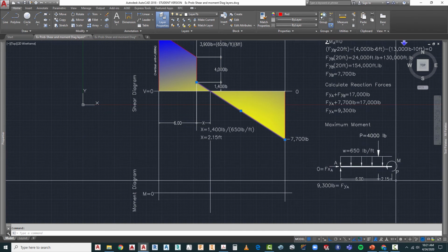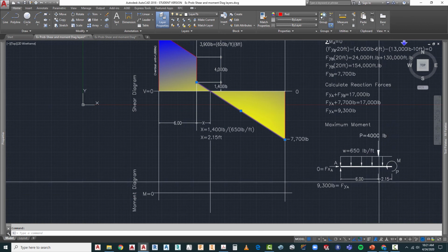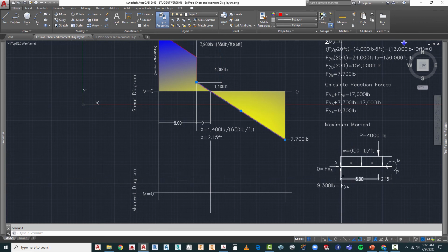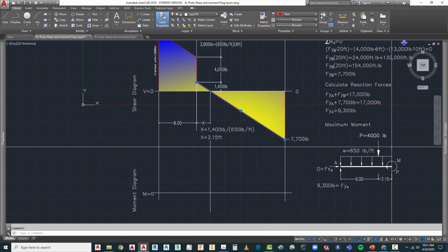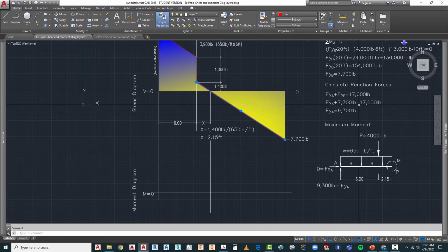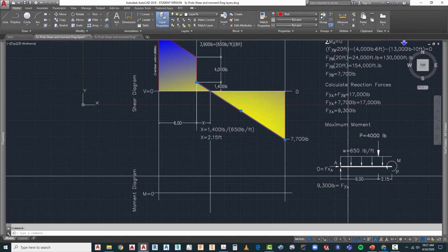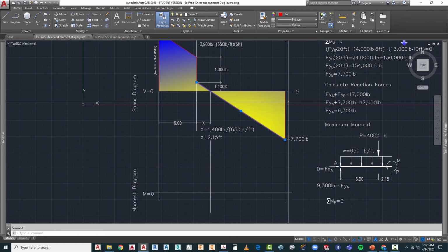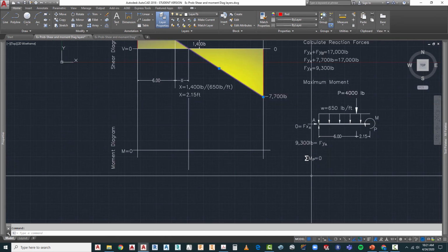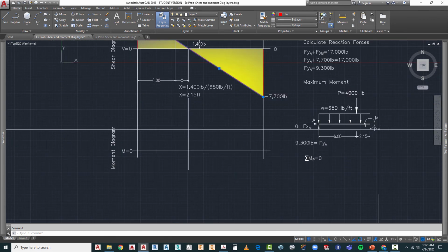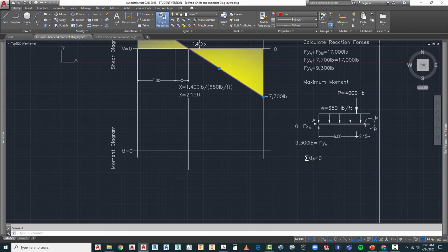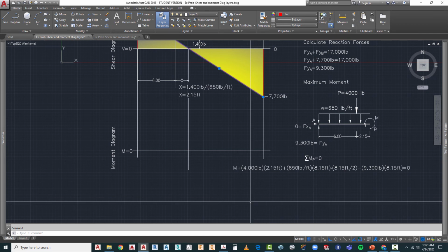So what we need to do is we have established where that concentrated load is going to be, and we have all the distance to the vertical reaction in here, which all of these forces need to counter. The horizontal forces need to be countered also. So the next step is to use our equation for the summation of moments around point P, so we call it MP. And we solve for the equation.